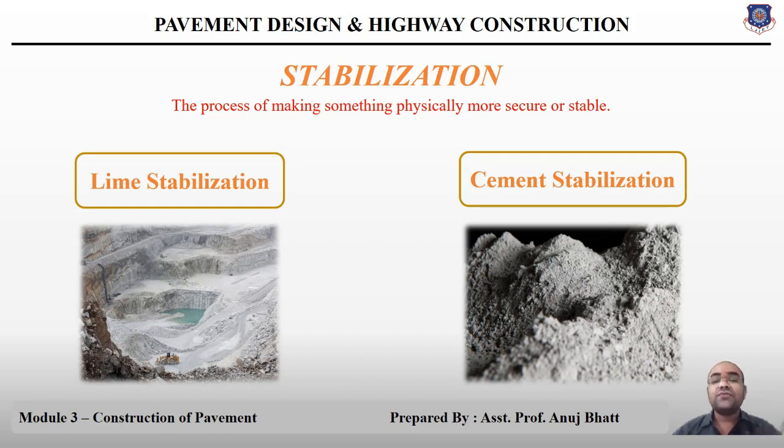There are various useful additives which improve the properties of soil cement, and those additives are lime, for clay soil, sodium hydroxide, sodium carbonate, and also calcium chloride.